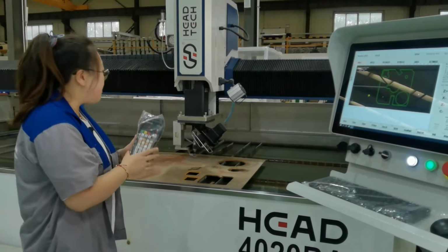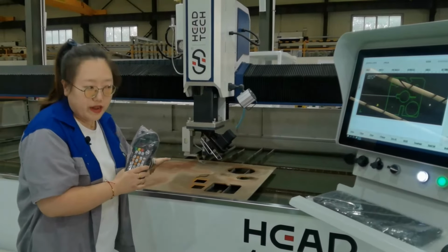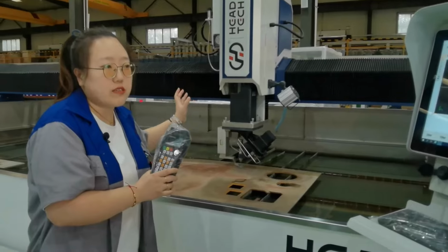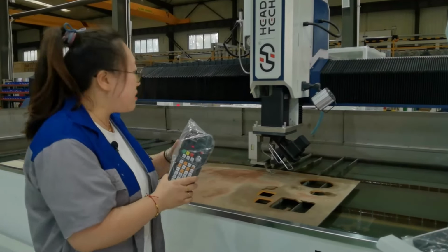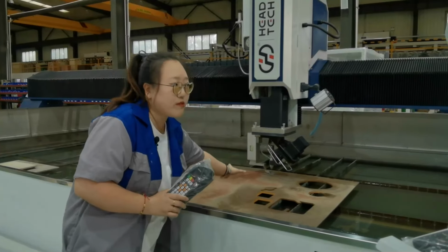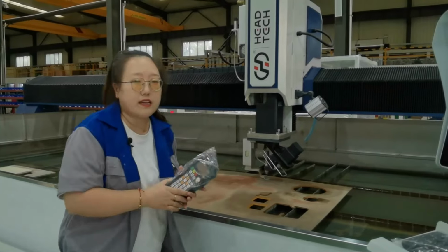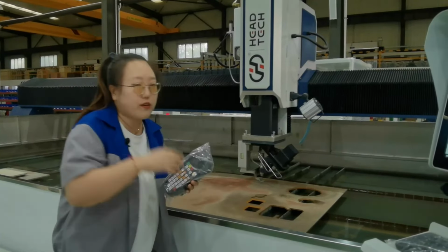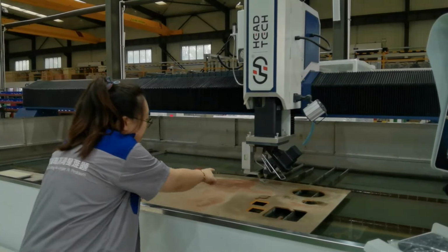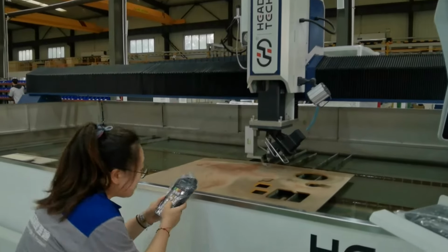And then after you have moved to the place, you need to adjust the Z axis up and down, because we need to guarantee the cutting head's height above the material. There is the 3 millimeter thickness, and you need to adjust the cutting head up and down.